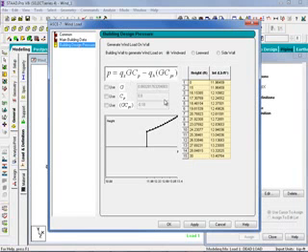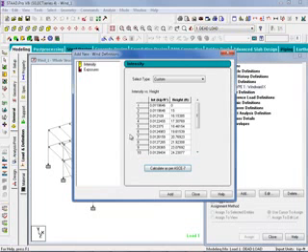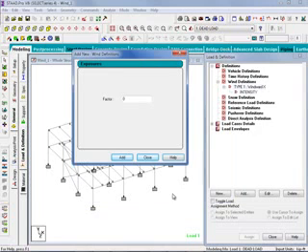This particular wind definition is applying for the windward wall, so I'll select the windward radio button, and then I'll click Apply, and you can see that my table's been updated, and then I'll click OK. And through that process, STAAD.Pro is able to populate this table using all the parameters I entered. Once you've completed adding the wind load definition, we will click Add, and you can see that our wind definition is now complete.